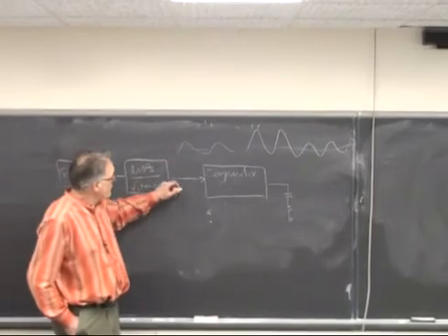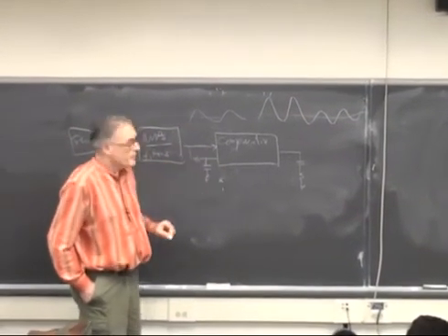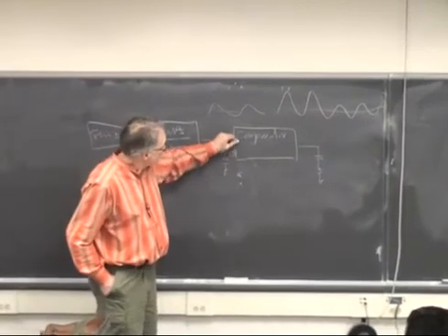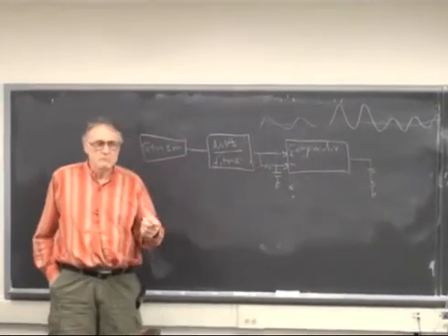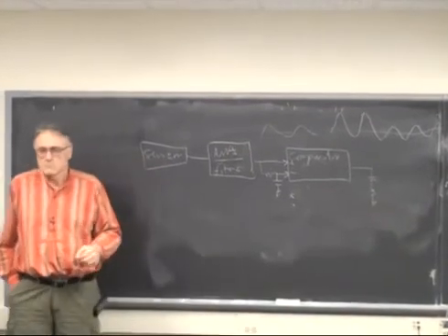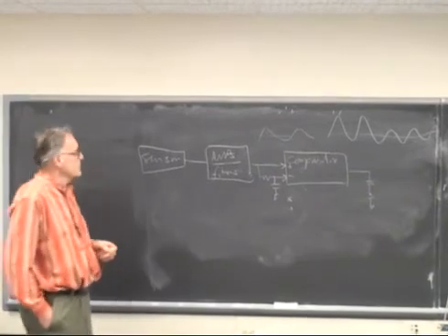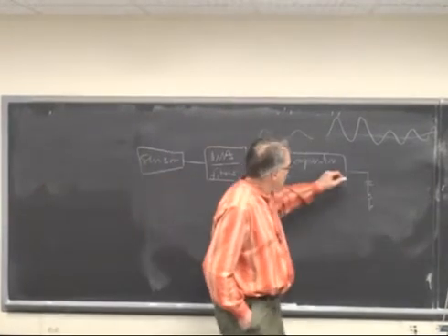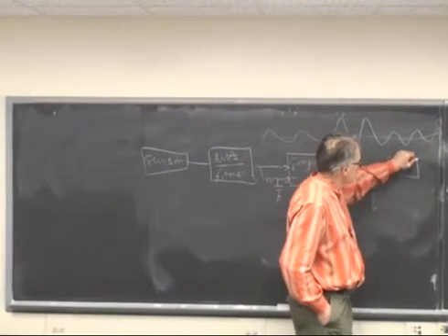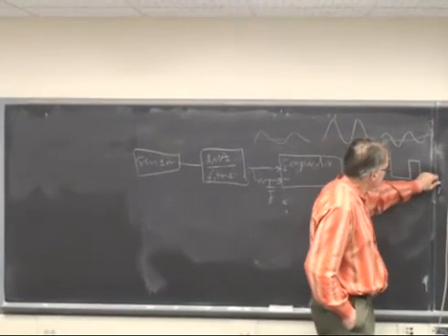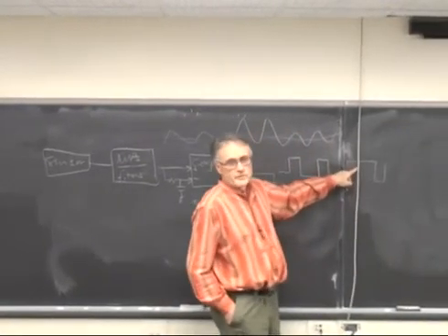So the other input of the comparator might be something that looks like a low-pass filter with a fairly long time constant, 5 seconds. So what's going to come out of here then is going to be pulse, rest, pulse, rest, pulse, rest. That's where you wiggled your finger.